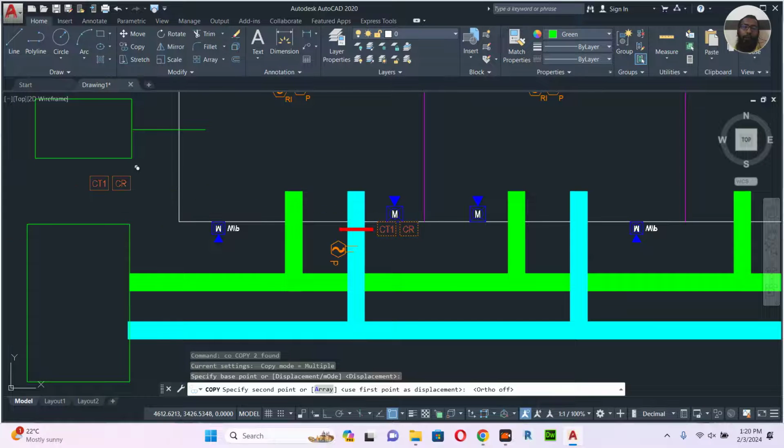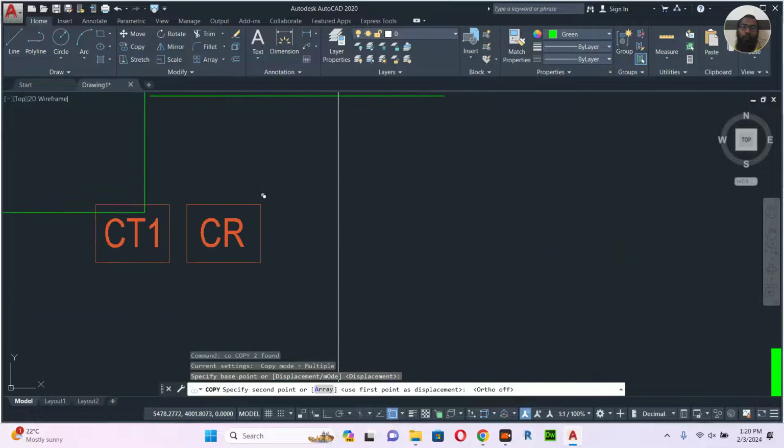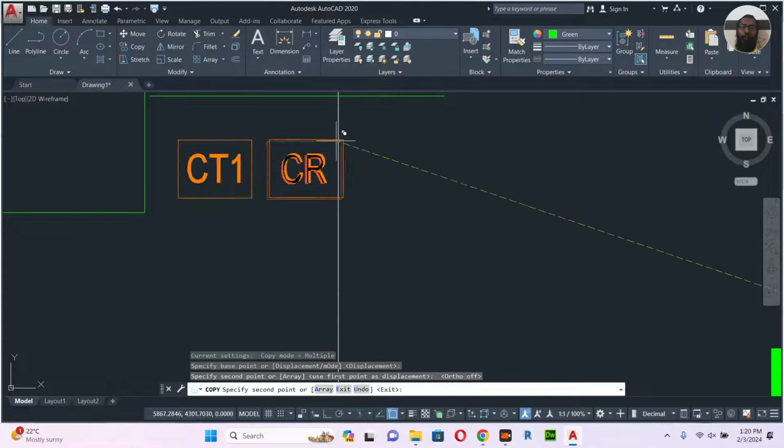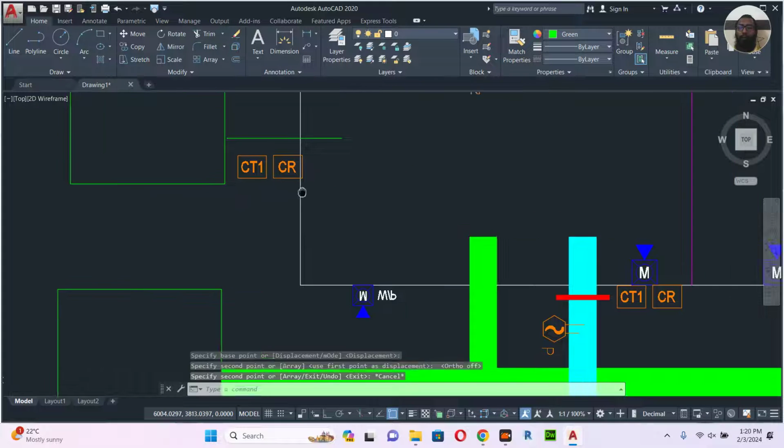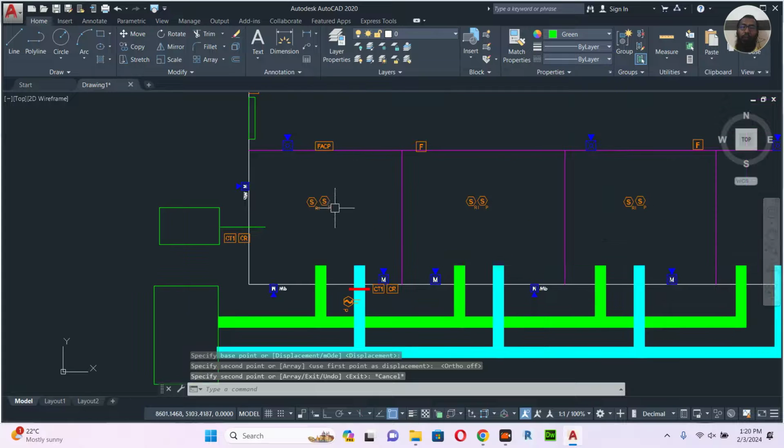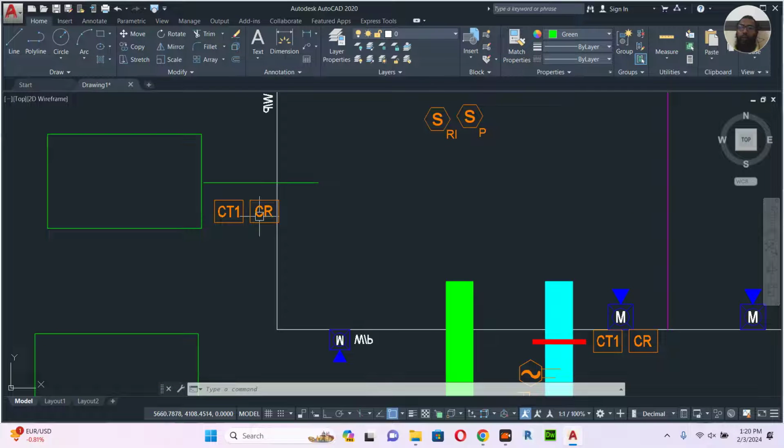So here there will be another two modules. Actually it's in the wall. So this fire alarm control panel gives a command here to close the motorized damper, and at the same time it will give a command to this control relay to trigger the exhaust fan.